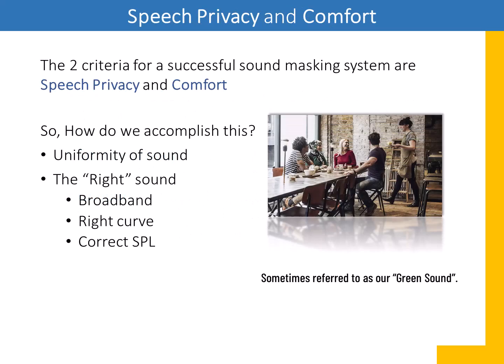The two criteria for a successful sound masking system are speech privacy and comfort. So, how do we accomplish this? We start with uniformity of sound. The right sound is broadband, the right curve, set at the correct sound pressure levels, or SPL.